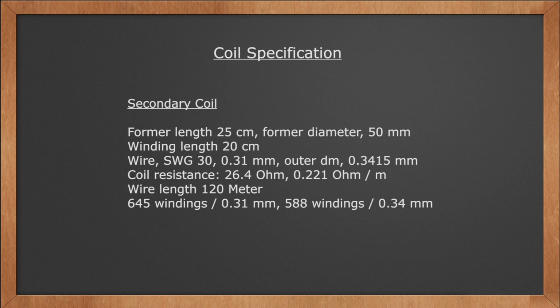All physical parameters of this DUT are measured without the help of an LCR meter. In order to calculate the resonance, we would need to find the parasitic capacitance as well as the inductance of the coil. The stray or parasitic capacitance of the coil results from the distance between each winding. This also changes over frequency. So the complexity of finding the correct resonance frequency is further influenced by dielectric losses of the former material, as well as the coating of the enamel copper wire and material in the close surroundings.